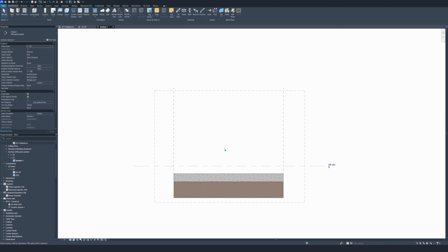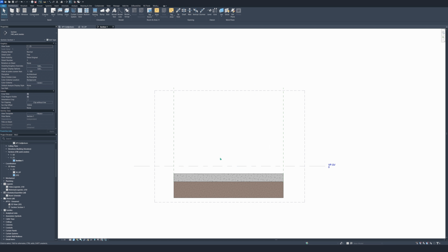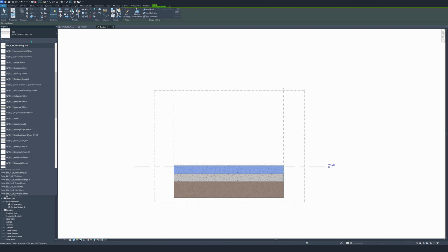Now we can do the insulation on top of it, but we can do it in two ways. We can go back to our ground floor and draw the insulation like we did with the concrete slab, or another trick I will show you that is faster. We're gonna select the concrete slab, copy by CO, we're gonna move it above, and now the trick here is by selecting the concrete slab, we're gonna change it to the insulation.